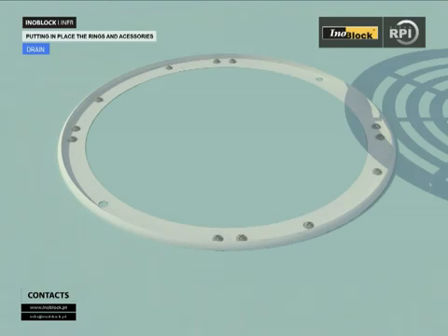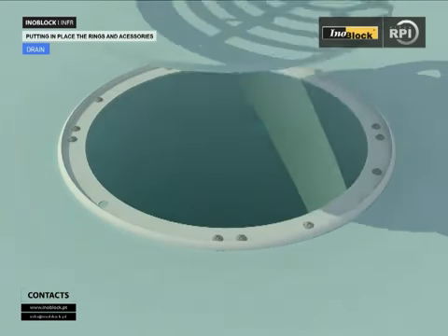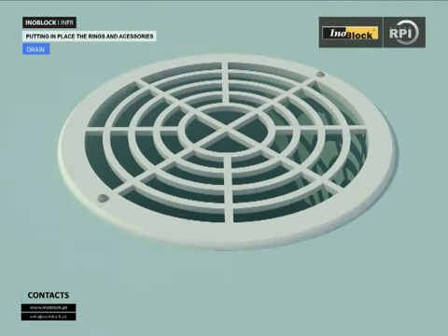Shut off the water and fit the drain securing ring with the screws provided. You can then cut out the circle of liner with a sharp knife and fit the drain cover. Care and attention are required when cutting out the liner.